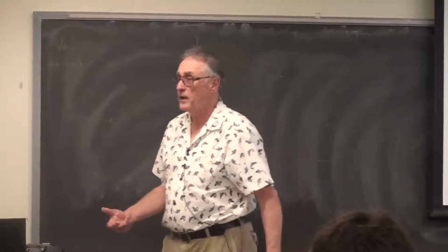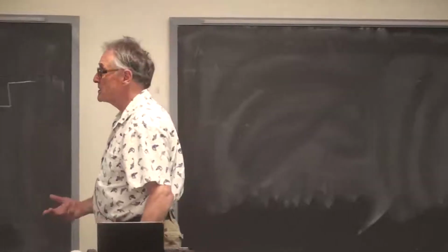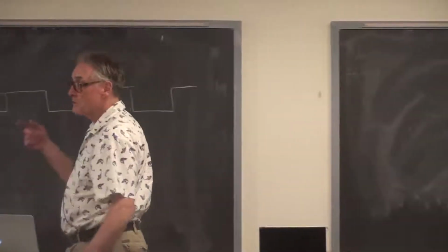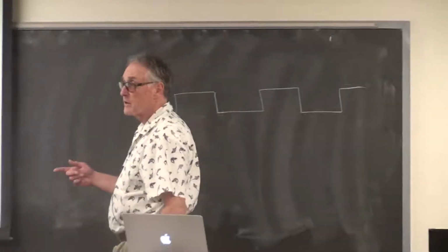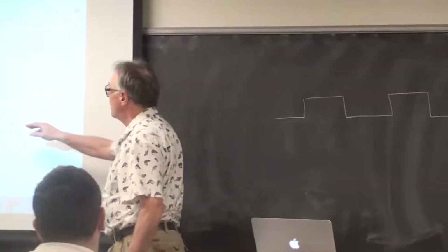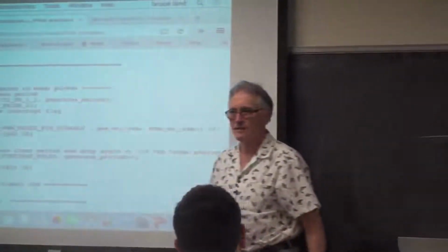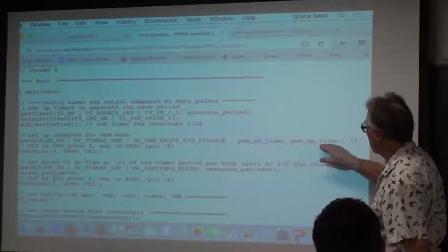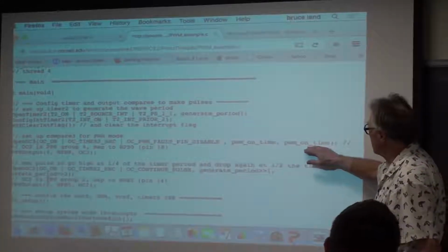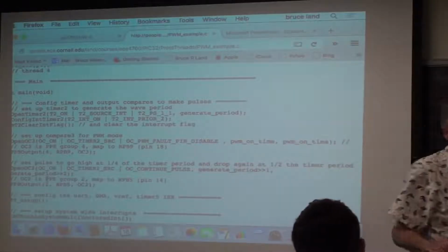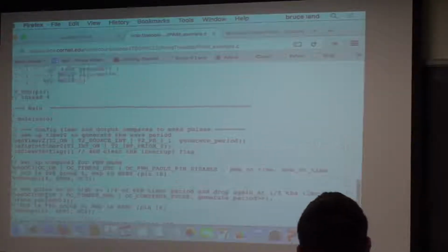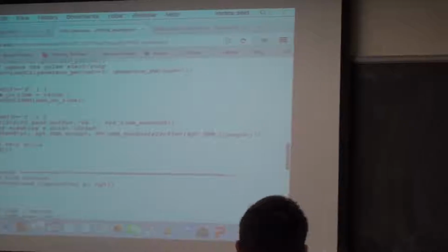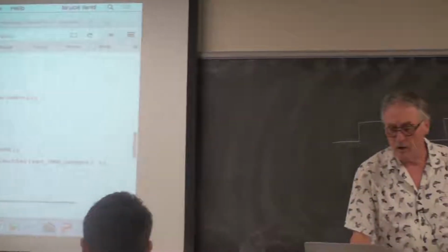And the PWM fault pin will signal to the CPU that there's a motor problem if you have a sensor on the motor. So I'm disabling it because I don't think we're going to have that problem. And then you can put any numbers in here you want, because the very next thing you're going to do, the third line of code that you need, is up here, which says